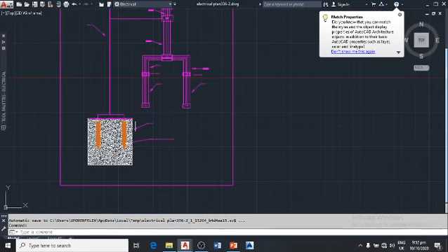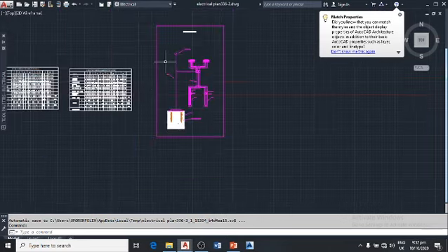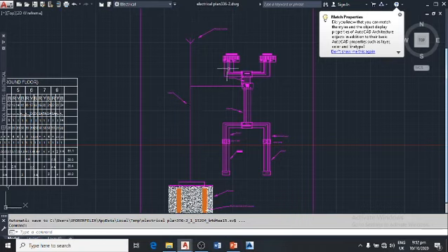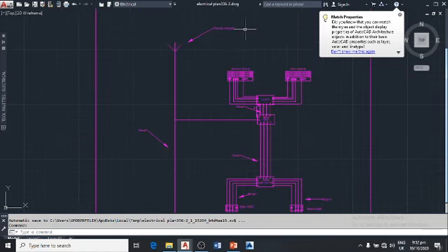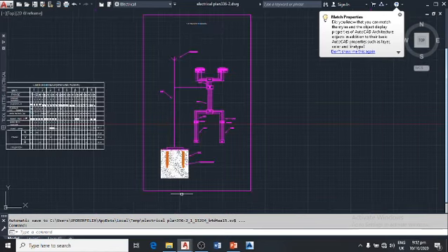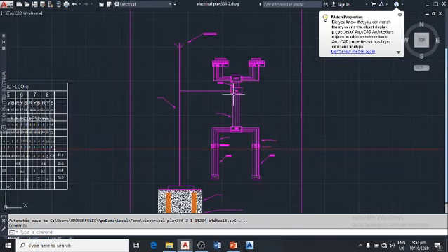By this, our appliances are not affected, our building is safe, people around the environment are safe because the amount of energy coming from the thunder and the lightning is arrested by the lightning and thunder arrestor and is taken down to the earth. Okay, that's how our earthing works, and that's the schematic showing the earthing connected to the rest of the circuit.